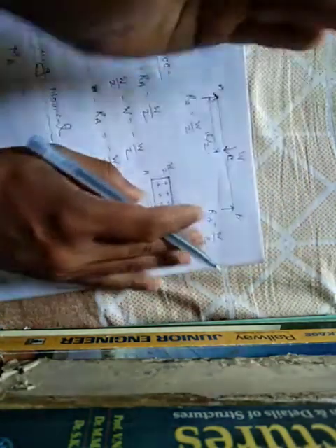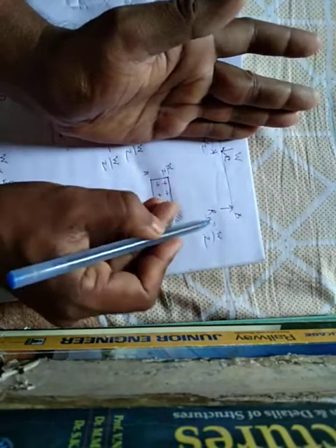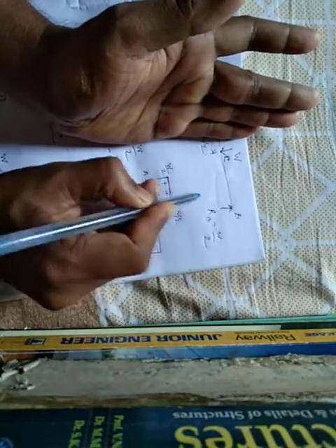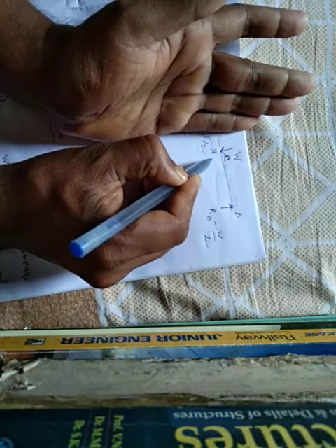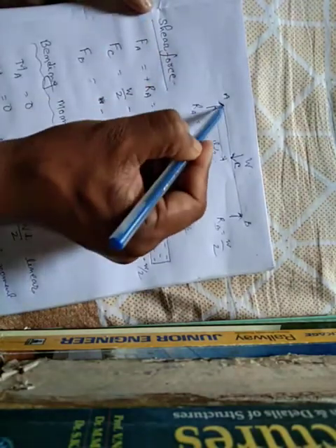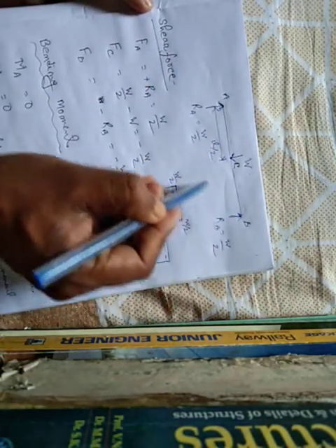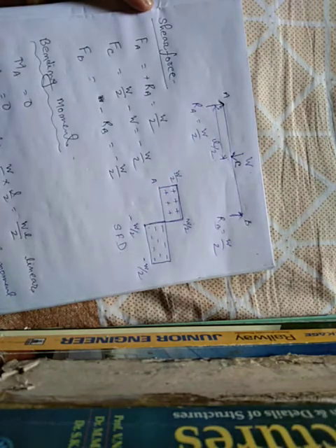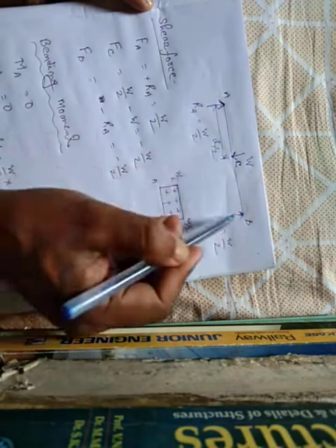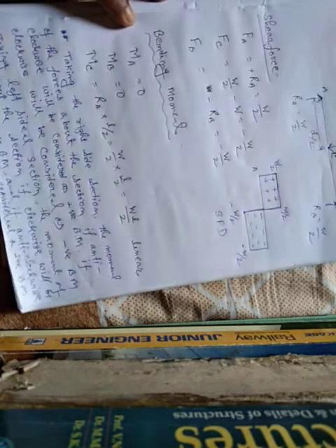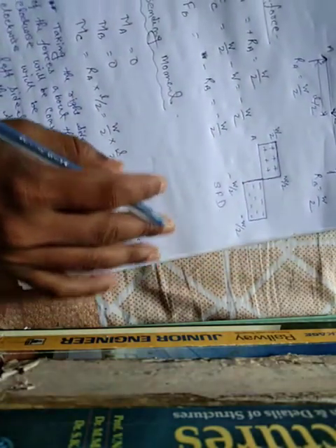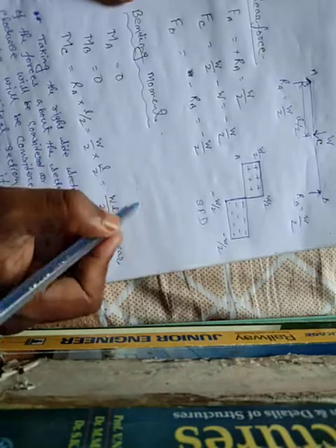In case I choose the right side section, the reaction force is upward direction. The moment at point C is anti-clockwise. That means positive bending moment. In both cases, bending moment is positive because the shape of the curvature is concavity. Let me draw the bending moment diagram.